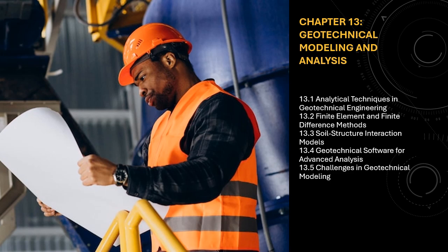Mitigation. Advanced dynamic analysis techniques, including time history analysis, response spectrum analysis, and liquefaction models, are essential for seismic design. Incorporating site-specific seismic hazard assessments and using nonlinear dynamic models can improve the accuracy of earthquake-induced behavior predictions.